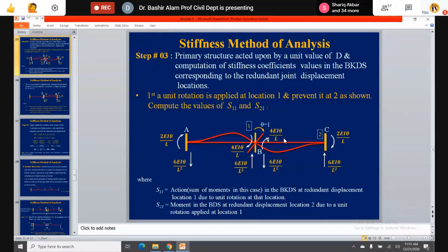So at the near end, once we know that it is 4EI theta over L, at the far end it will be half of this magnitude and in the same direction. If it is clockwise at the near end, the far end will also be clockwise. The rest is simple mathematics, how we balance this couple, so you can find out these support reactions. These actions you can find out very easily then. Any question till now? The only point is we will have to prove how this 4EI theta over L is coming. Is there any question?